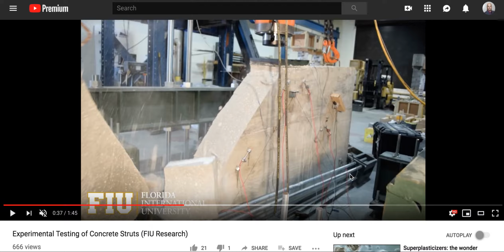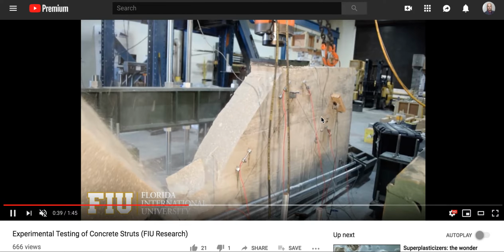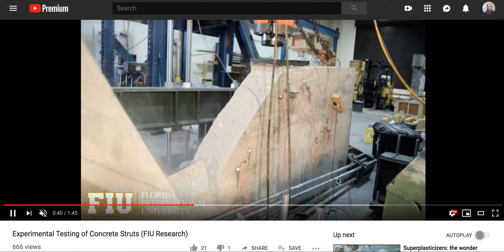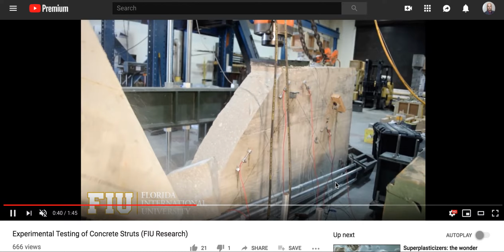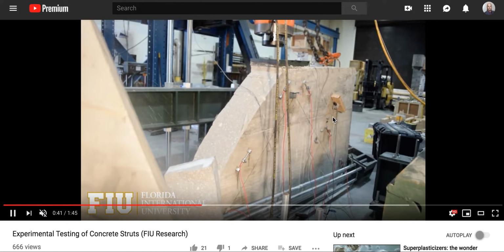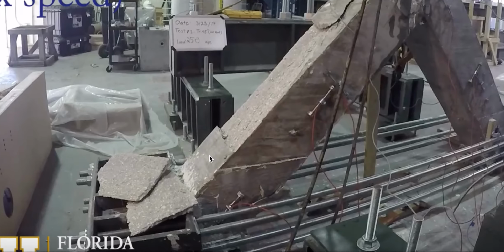I would love to know what the force is down here. But again, this is still in place. So even though it's 557 kips at this failure, if you configure this to work on a bridge, you would still have it. I love the redundancy that I think of is you make a shelf. So if this failed, it would drop down to the shelf, not just fail, period. Now, this is 717 kips, but we no longer have the luxury of the other detailing.